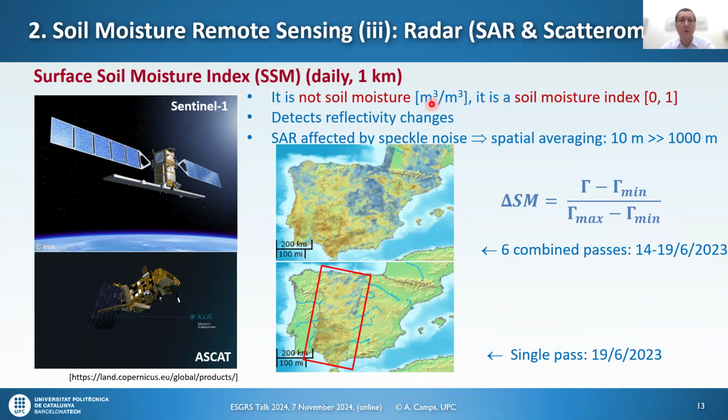because also the soil moisture, as cubic meters of water per cubic meters of volume, also goes from 0 to 1. Actually, in real soil, it will go from 0, when it is absolutely dry, up to 0.4, in some cases a little bit higher, but not much higher than 0.5 in some instances. That depends on the porosity and the density of the soil and the grain size and all this.